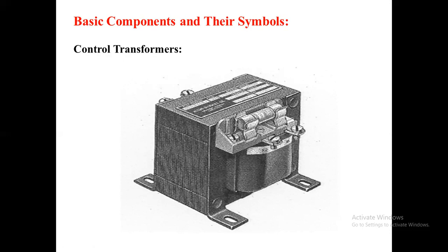For safety reasons, machine controls are low voltage components, because the switches, lights, and other components must be touched by the operator and maintenance personnel. This means the line voltage must be reduced to 120 volt AC or less for the control. This is done using a control transformer. This figure shows the electrical diagram symbol for a control transformer.